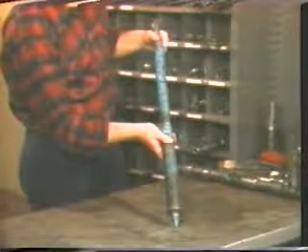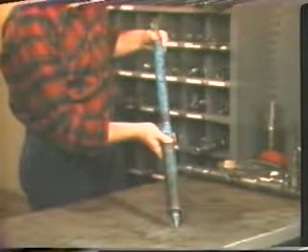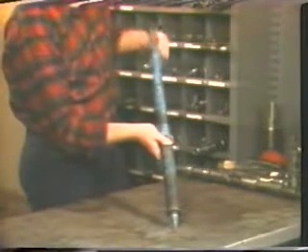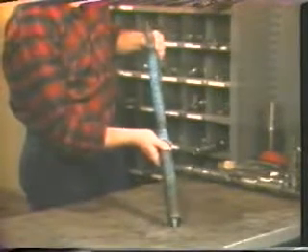Some tools are designed to both locate and retrieve the wire line during one trip in the well. These tools are called wire retrievers. The oldest and most popular of the wire retrievers consists of a mandrel, which has a spear point on the bottom, and a slotted skirt which floats over the mandrel. The ID of the skirt and the OD of the mandrel are machined to have matching tapers, which, when the skirt moves down over the mandrel, will wedge the wire line between them and grab the wire.